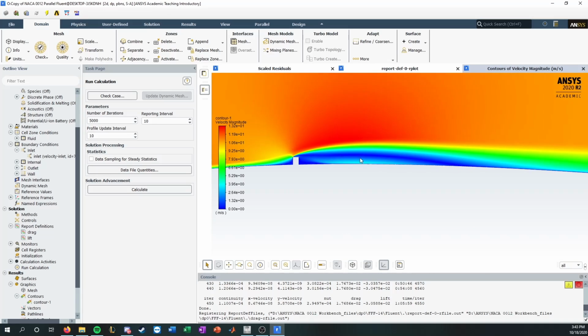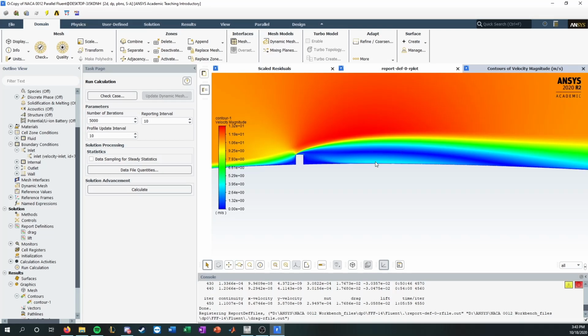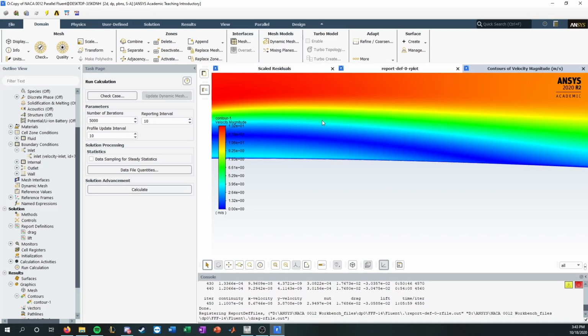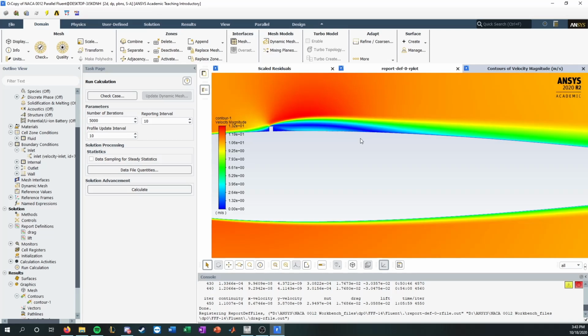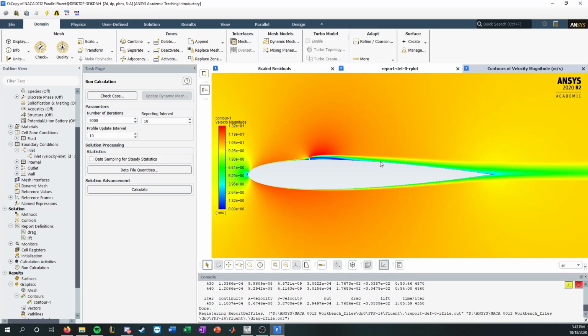And so it's pretty interesting what's exactly going on, and I could be totally wrong because you don't actually see a clear separation, like a recirculation zone. You kind of see it get as if it was a recirculation zone, but some of that eventually gets pushed over and rejoins this top surface. So it is like this mixture of a recirculation zone, of a separation, that then gets reattached because of an external flow. And so you don't actually see this in a steady state problem. To backtrack, I guess there's many things why this doesn't work. Another thing is because it's steady state, and in reality, anything to do with turbulence is a little bit iffy when you run it in steady state.